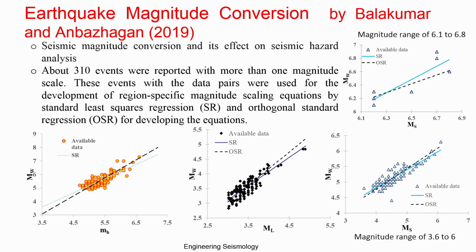We took the northeast as a seismic study area and tried to get a seismic study area map based on the intensity, collected different earthquakes and tried to generate our own regression model, and then took previous models to assess how this model conversion will affect your number of data. Then how the a and b parameters will be affected. The a-b parameters will be discussed in the coming classes, and then how it really affects your hazard values. That is all we studied by taking this paper.